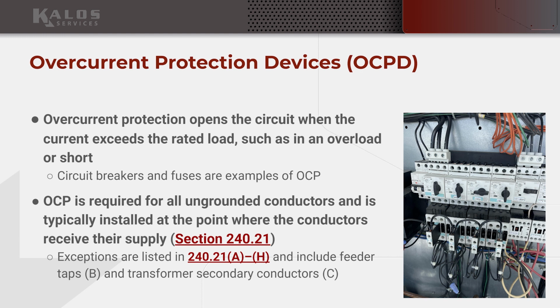So when we complete that circuit, we're going to have a very high amount of current. And the reason we're going to have a very high amount of current is because the only resistor in the circuit is our grounding conductors, our equipment grounding conductors. That's the only resistor in the circuit. And because they're great conductors, that resistance is very low, which means current is going to be very high. And overcurrent devices are designed to open under those circumstances. And so great, we've grounded everything. We have primary overcurrent protection and secondary overcurrent protection. We should expect these devices to open, so long as it's all been wired up correctly.